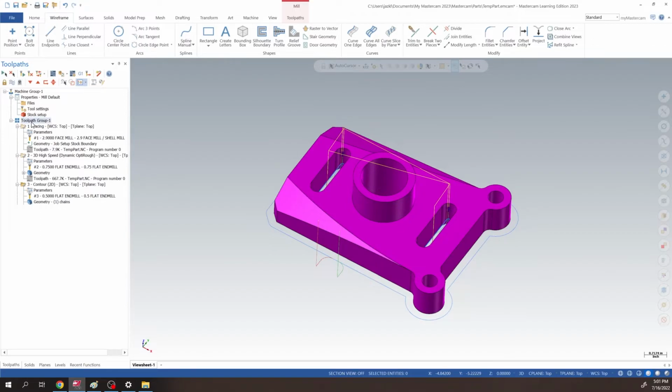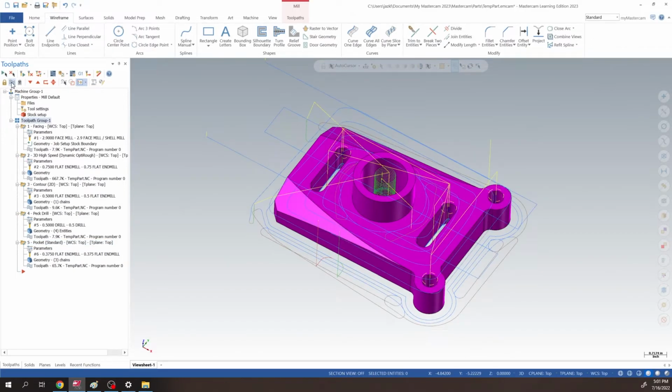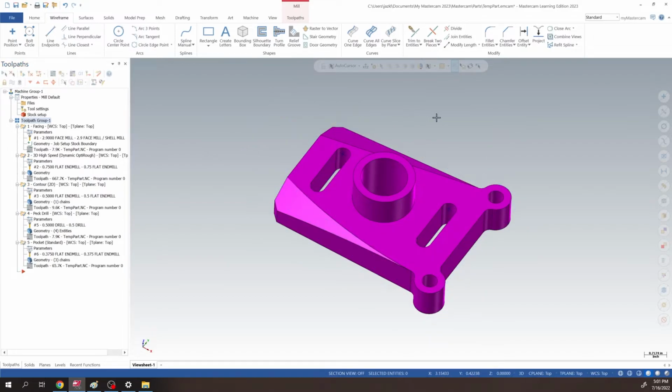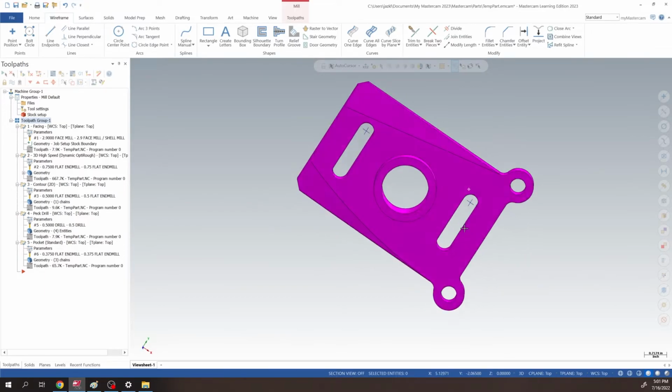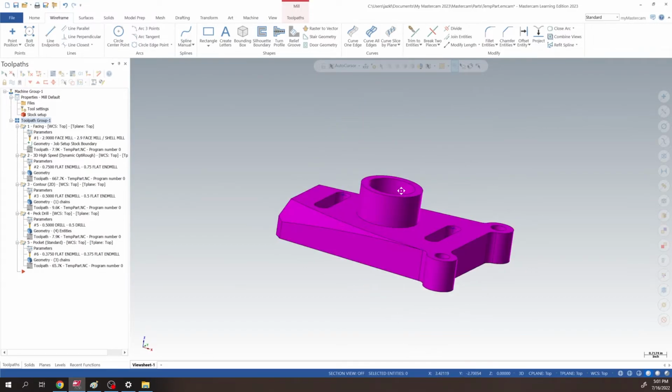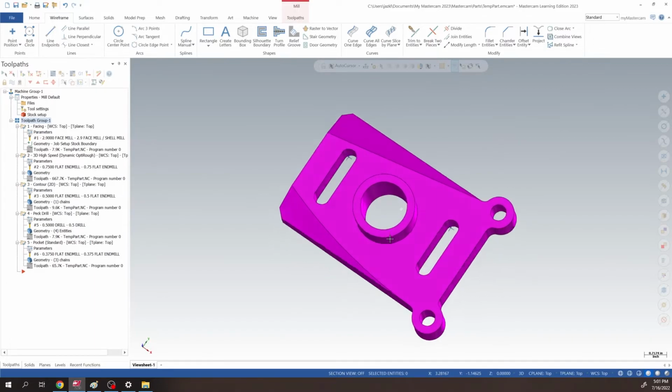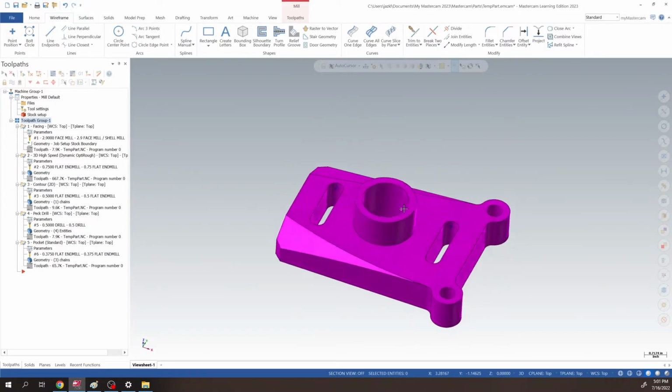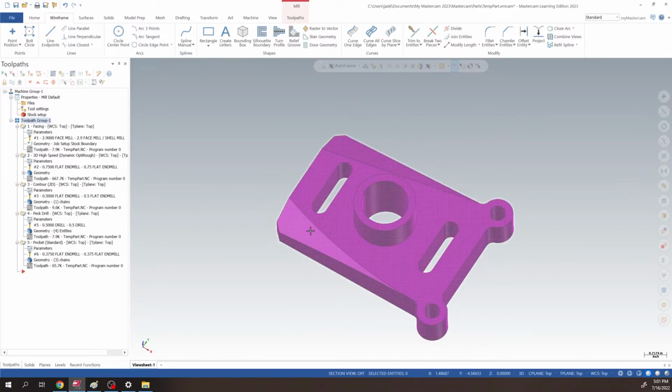And now I'm going to click my toolpath group, and I'm going to turn them on, and then I'm going to hide all the tools. So far we have, we're facing it, we're roughing out a lot of the material. We're doing our outside profile. We drilled these holes, and we took care of our pockets here. And the roughing also cleaned out this hole, but it did leave 20 thou extra material, so the ID's probably about 40 thou too small.